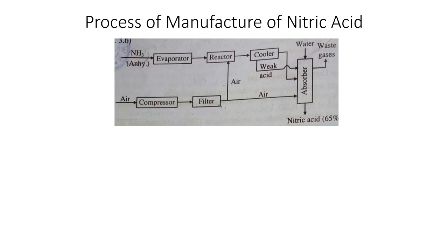So that ammonia cannot be used directly for the manufacture of nitric acid. Ammonia prepared by Haber's process is to be scrubbed in sodium hydroxide first, and then freed from water, meaning it is purified. How is it freed from water?